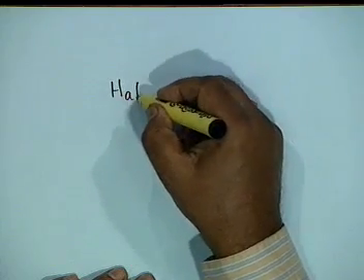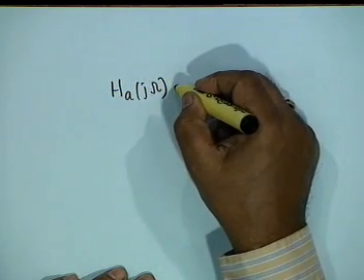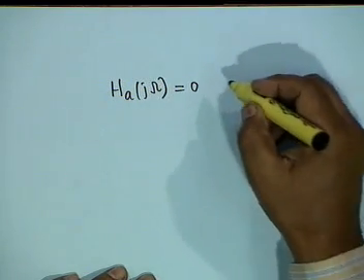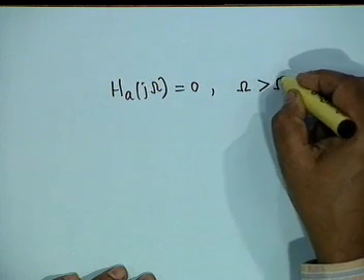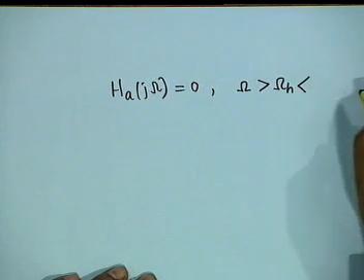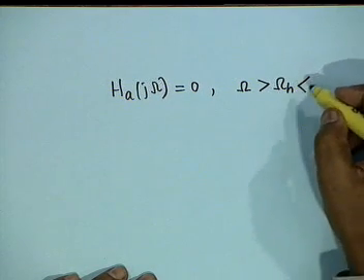With this normalization, that is h of n equal to T h a of nT, and a band limited transfer function, that is Ha of j omega is 0 for omega greater than omega h, which is less than pi by capital T, sampling theorem must be obeyed.